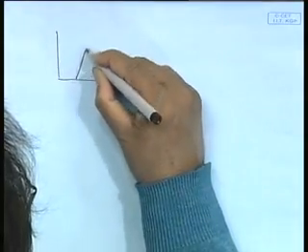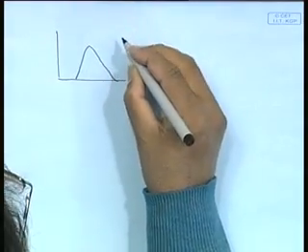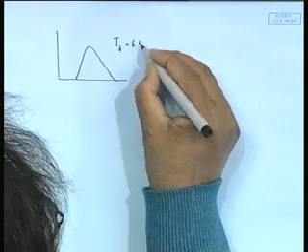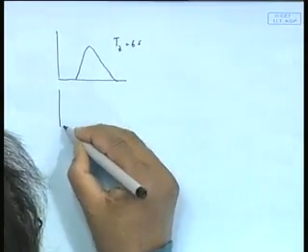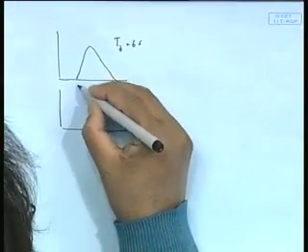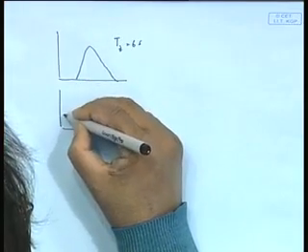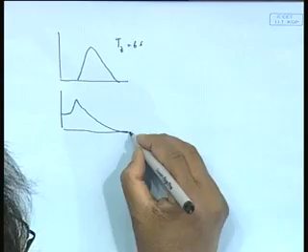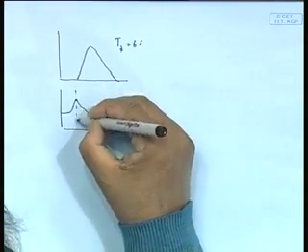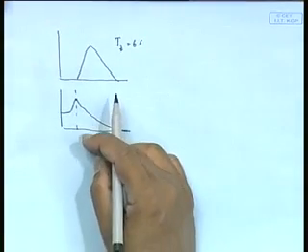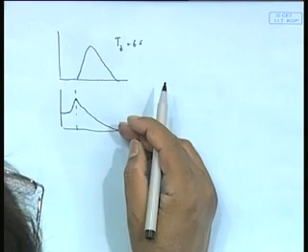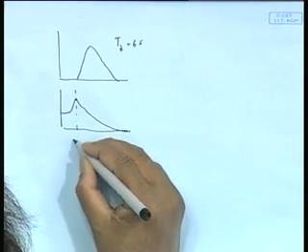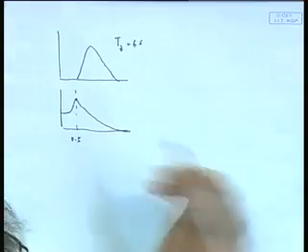Take a spectrum, it is like that. This is at 6 seconds, a peak period of 6 seconds. Let us say this is at smaller wavelet, say Tz is 6 seconds, and certain H 1/3 is there. My RAO does not change. Remember, RAO is something like this diagram. It is peaking here. This is my peak response, which is probably equivalent to 0.5 here, means 2 pi by 0.5, about 12 seconds, around that, let us say.